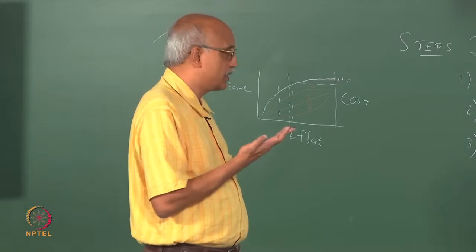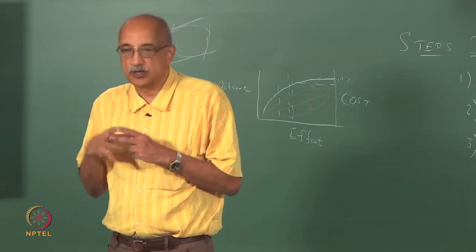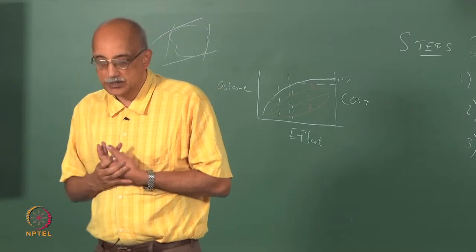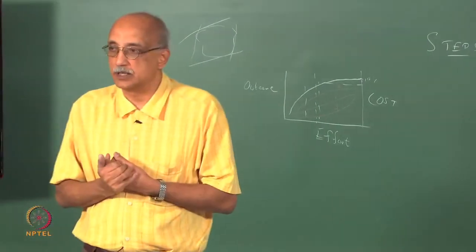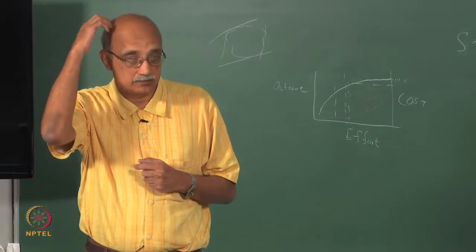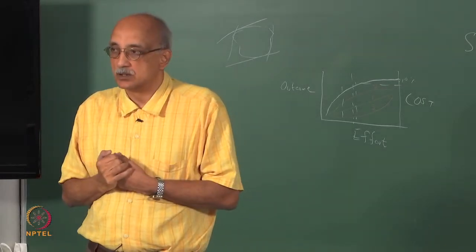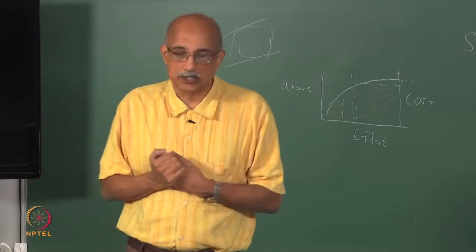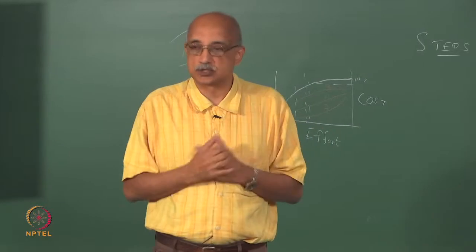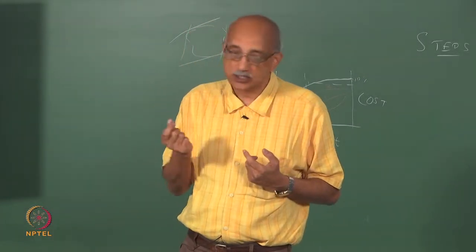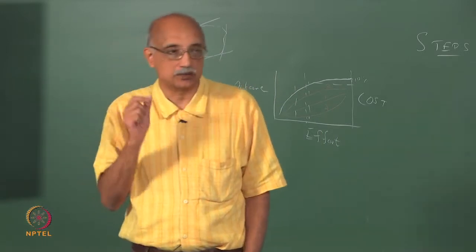The way this works is you measure shape based on its effect on some functionality. For example, let us say that you have a powder that you are trying to pack into a bottle. Compressibility is a major parameter, porosity and compressibility, which go together. So, what you would try to do is measure porosity as a function of compressive force, and it turns out that compressibility is actually a measure of particle shape.